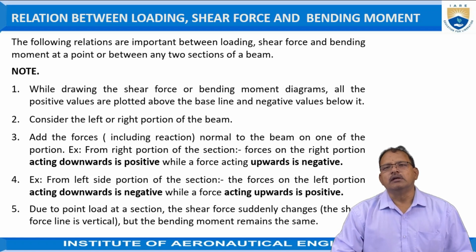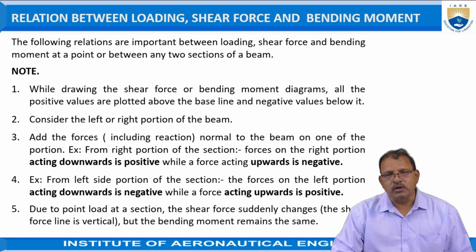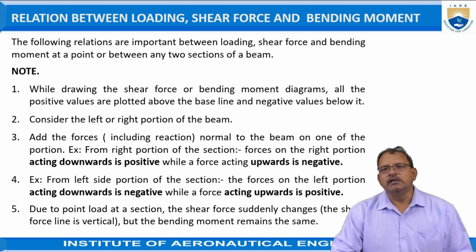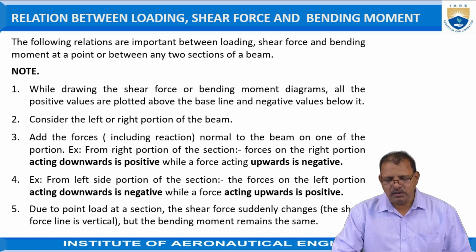Consider the left hand or right hand portion of the beam for drawing the shear force as well as the bending moment. Add the forces, including the reactions, normal to the beam on one of the portions.